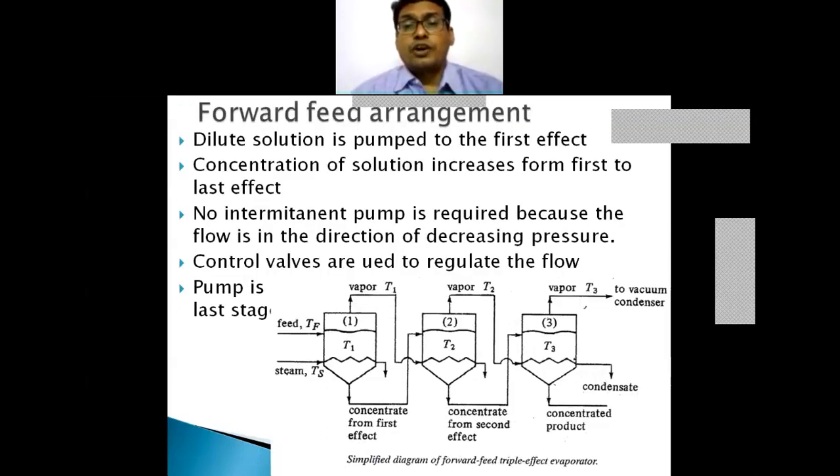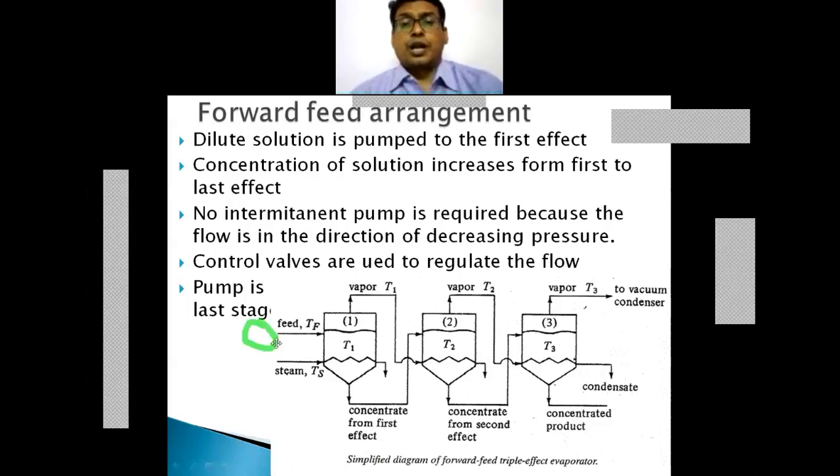Now the forward feed arrangement is a parallel flow arrangement. So dilute solution is pumped to the first effect. Here you use the pump to transfer the feed into the evaporator.